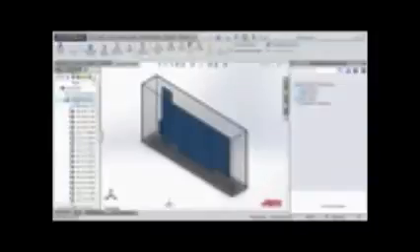We have the ability to go back and change the thermal representation of a component or change whether you are modeling it as a detailed or compact board. In the components tree, click on the board and then hover over this green button. You will see that it says Edit EDA Data. Clicking on it reopens Flow EDA Bridge on this board. You can also update components within Flowtherm XT.